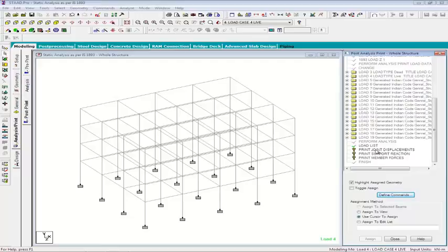We have to display the joint displacement for all the nodes in the structure and support reaction for all the supports. So we will select the joint displacement command and apply it to the view, which will apply the command to the whole structure. And again, the support reaction has to be applied to the whole structure.